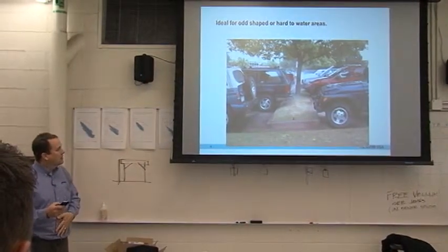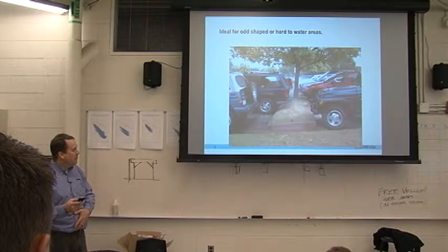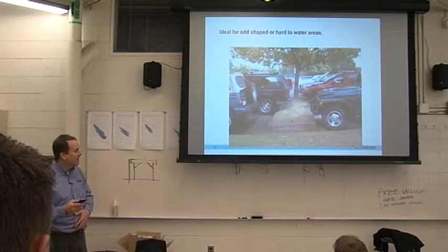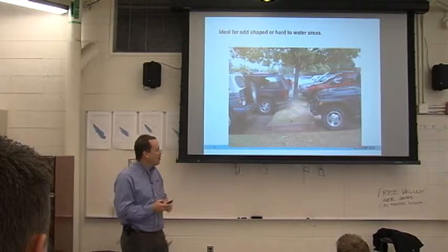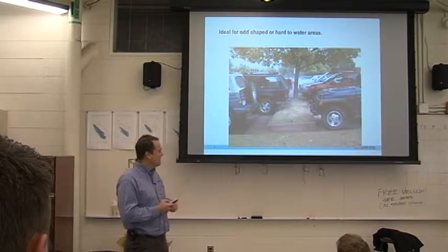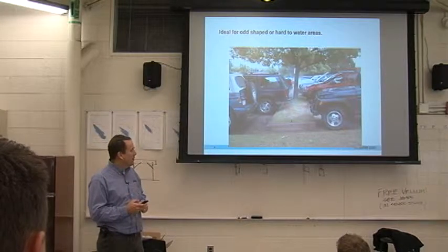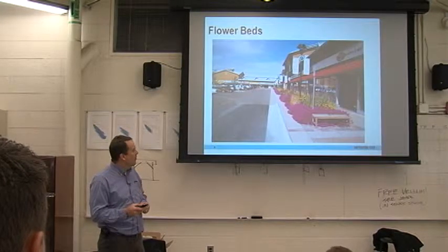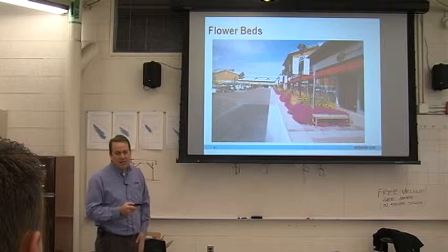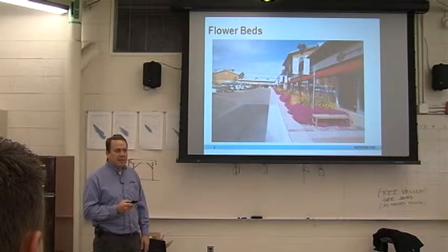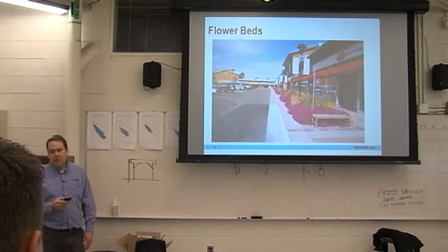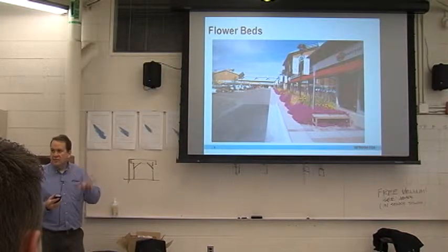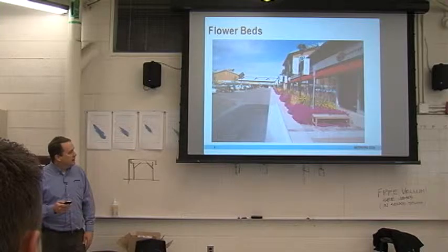Okay, this is one of my great designs, grass in a parking lot with spray heads right behind the back of the curb, so that when that comes on, the cars block the sprinklers. It's just the real world out there. We run into some really unique areas that we're dealing with. Flower beds, they're always very difficult to irrigate because they tend to grow over a large area and can block our overhead irrigation that we're trying to irrigate with. And so drip fits that fairly well.